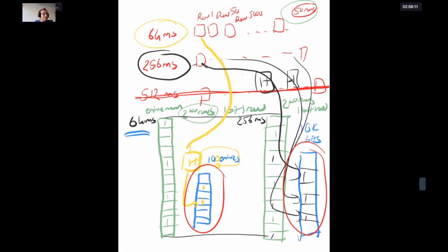This is the result of the profiling. The profiling fills these bins in the data structures, and then the memory controller asks the question, oh, I have this row address I want to refresh. How often should I refresh it? Basically, the memory controller goes through the hash function for the row address, checks this bin. If its bits are set to 1, it refreshes every 64 milliseconds.